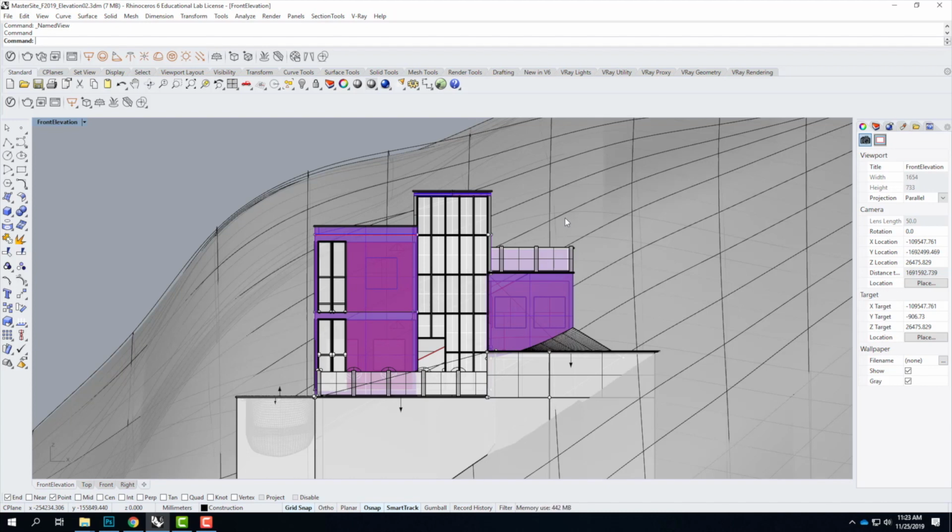And we're going to use a command to do this called Make 2D. And I would say that this is probably second to maybe Project, one of my favorite commands in Rhino. It's very, very cool to be able to create a line drawing from whatever view that you see. This, by the way, doesn't have to be limited to just a flat parallel projection. You could create a line drawing out of any perspective in the same way. Furthermore, the line drawing that it creates are all live lines. So when we get into Illustrator, we can manipulate the lines, we can work with them, etc.